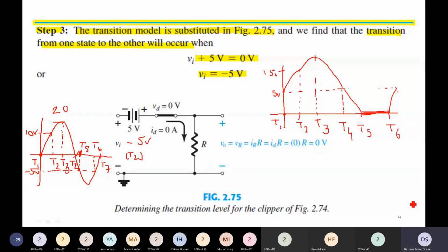So not only have we removed a portion of the negative signal, that is minus 15 volt, we have also level shifted the waveform. And this level shifting can be observed at time t3, where the input voltage is now 25 volts. And this is the level shifting. It is occurring at time t3. In fact, it is occurring throughout the waveform. But the concept of level shifting is that we level shift the input voltage with the help of an external DC power supply.